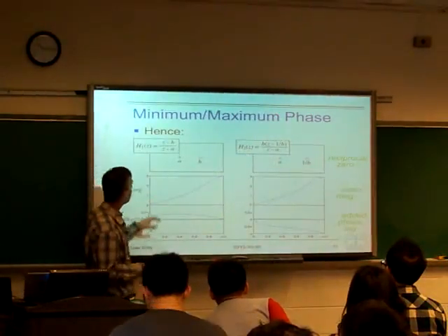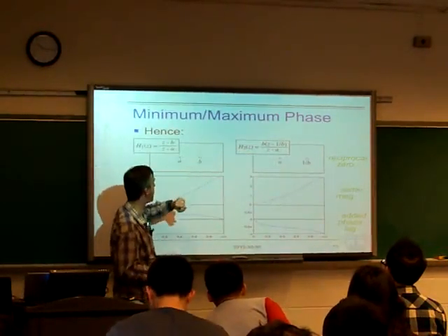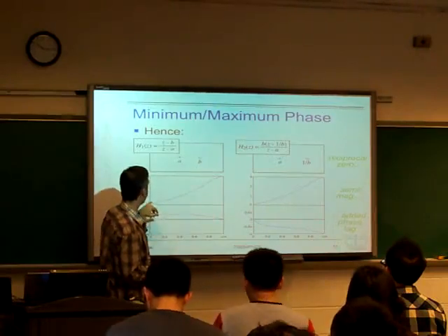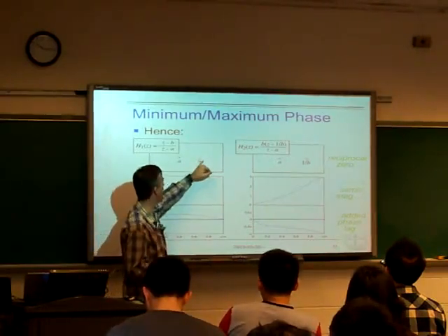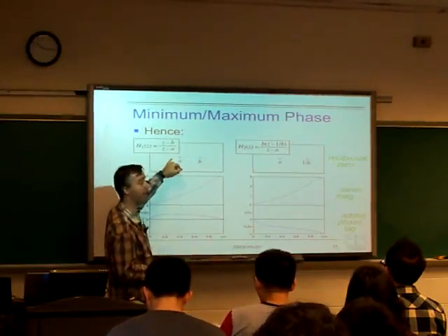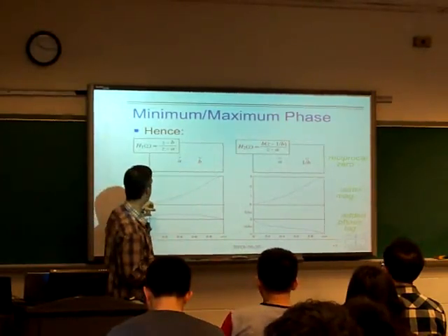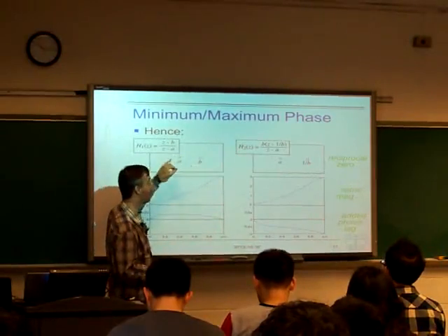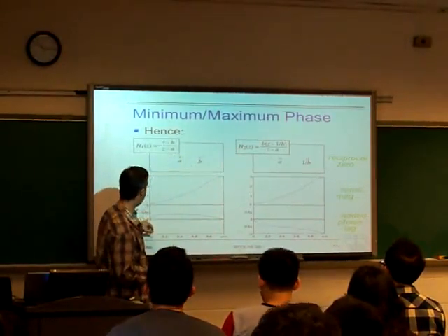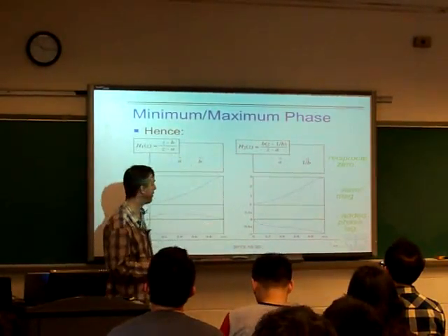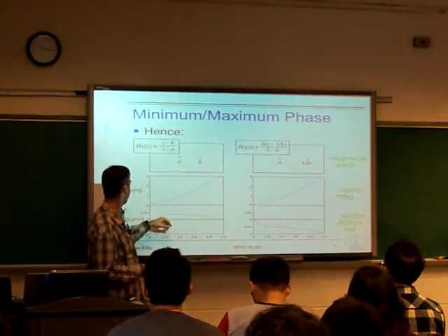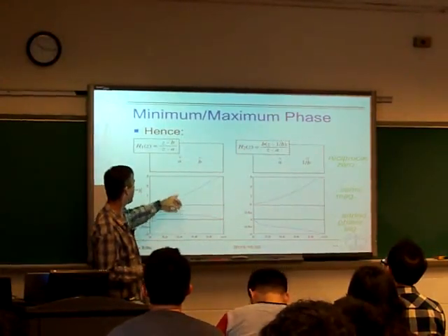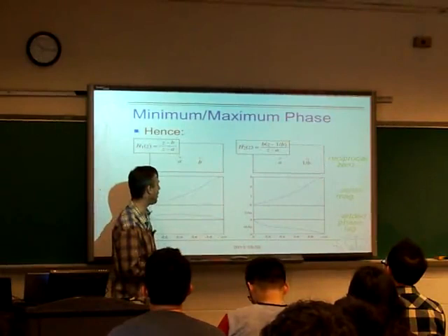But here's an example with one pole and one zero. They're both inside the unit circle to begin with, and because we've got a zero near DC and a pole somewhat near the Nyquist frequency, it has this kind of high-pass response that it tends to cut these low frequencies and boost these high frequencies. But it has this nice, well-behaved phase response. There's a little bit of phase advance for intermediate frequencies, but mostly quite close to zero.